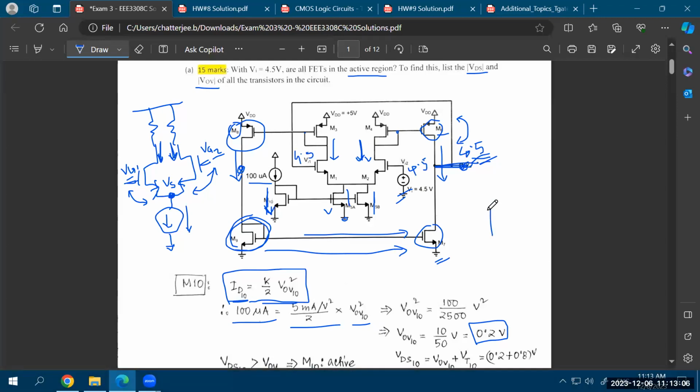Okay. So that goes back to this theory that if you have an amplifier, let's say 2 inputs and 1 output, and you feed back this output to the negative terminal, that becomes a unity gain feedback, right? Again, think about the op-amp circuits that you had studied during your homework number 2 or 3 and during your exam 1. So this is a unity gain configuration, right? So if this is your input voltage, the voltage at the negative terminal as well as the voltage at the output will be the same. So if this is V in, at the output side, you'll also see V in.